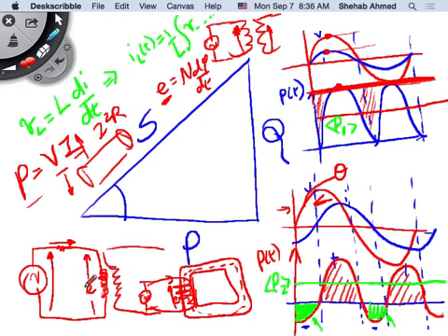How about if there is no voltage generated? If there's no voltage, then what's the value of current? It's this voltage source divided by the impedance of this wire, which is very low, right? So you've put a voltage source across a piece of wire. In this case, because it's DC, there's no time varying flux, and there's no back EMF generated, right? But if you put an AC voltage waveform, it pushed AC current through the windings,